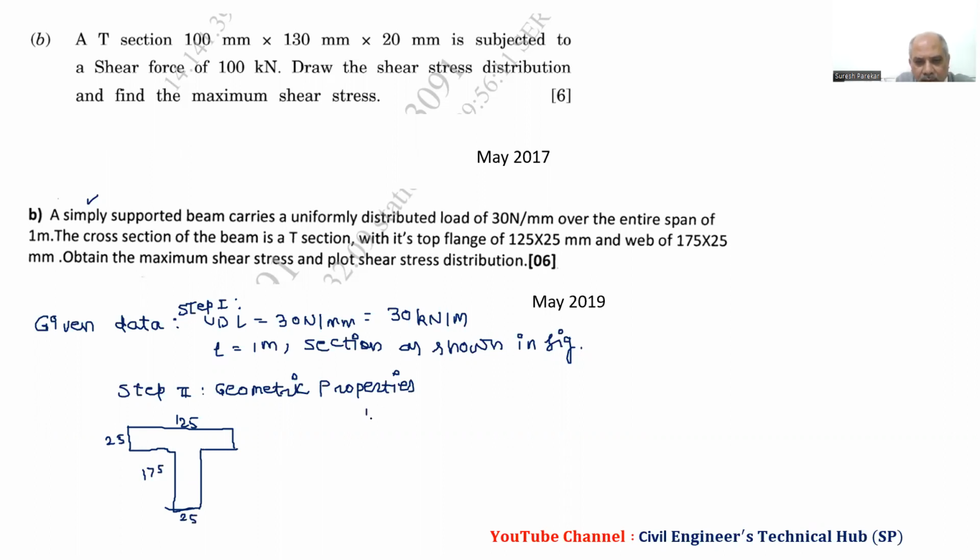Now Y bar from top is 125 into 25 into 25 by 2, from center to top, plus 175 into 25 into the distance from center of this till this.